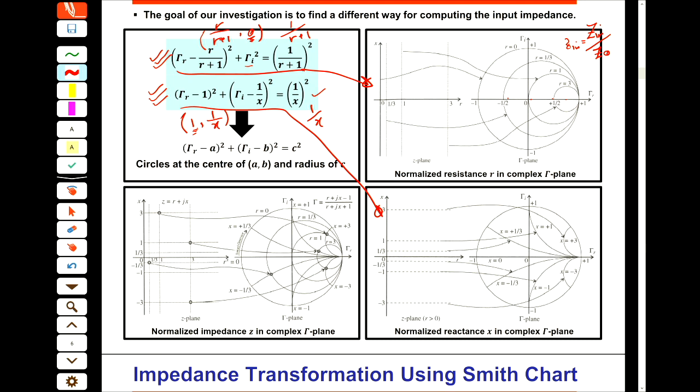All right? Again, if I'm looking for an impedance whose imaginary part equals 1, then it is somewhere on this circle. Or the imaginary part equals 3, actually 3 z naught. 100 plus j150 is here. If it is minus j150, it is on this circle. And I just want to tell you that we don't have negative r, because resistance can never be negative. We always have positive resistance, but the imaginary part could be positive or negative.